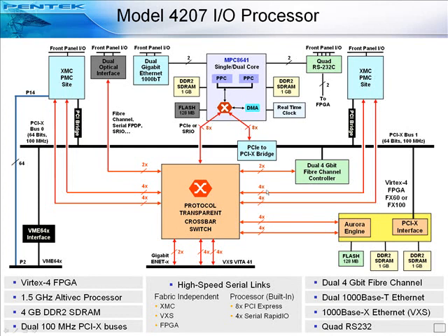In the center of the diagram, you see a gigabit serial crossbar switch, which is connected to the PowerPC, which controls all of the switch ports. It allows the crossbar switch to join any two switch ports together, providing an extremely flexible interconnection scheme for all of the major resources on the board. The crossbar switch is protocol transparent, so it can handle virtually any gigabit serial traffic.